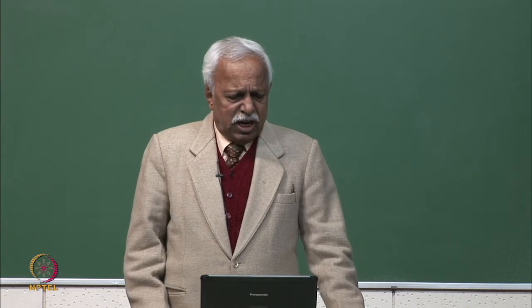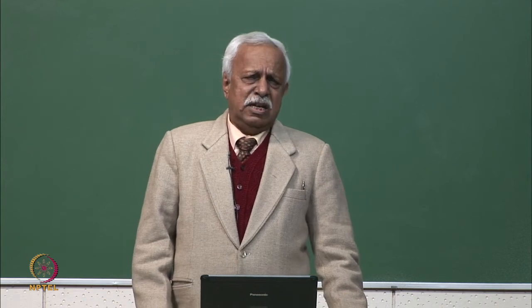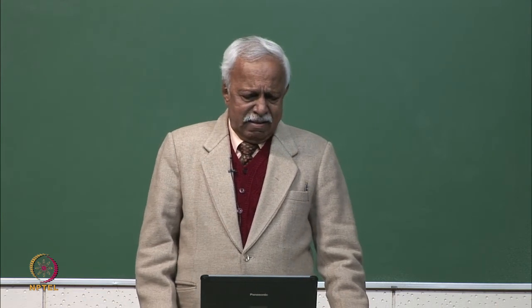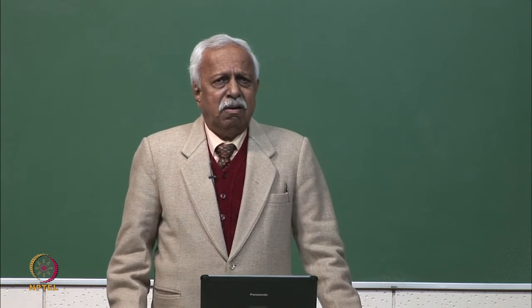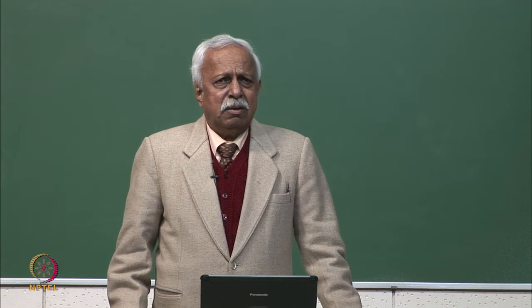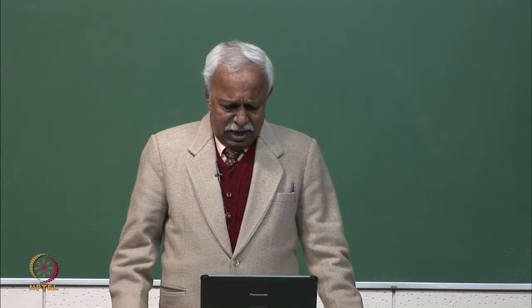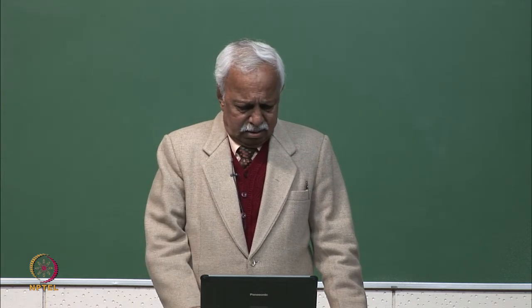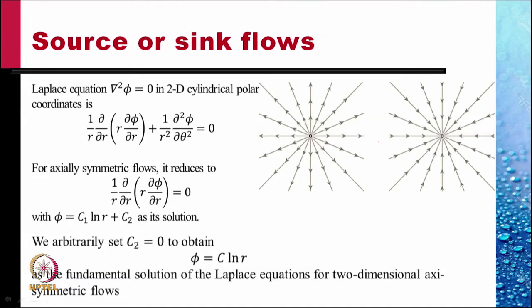So we can set C2 as 0, and then the velocity potential is constant times ln r. This is the fundamental solution of Laplace equation for two-dimensional axisymmetric flow.